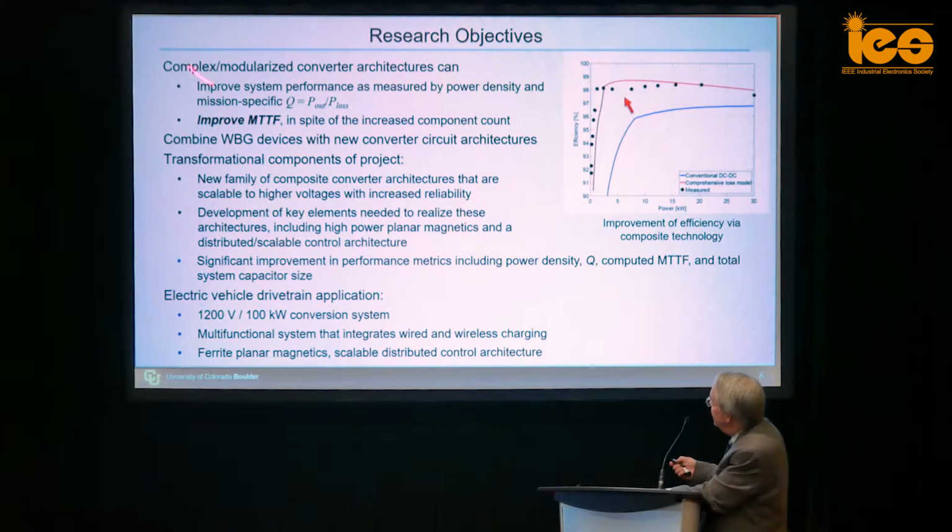We can measure the technology really by this combination of loss or Q, as well as cost and power density. And the claim is that even though it's more complex, it's worth doing because we get these performance benefits, and even though it looks like on the schematic there's more parts, we improve the reliability.